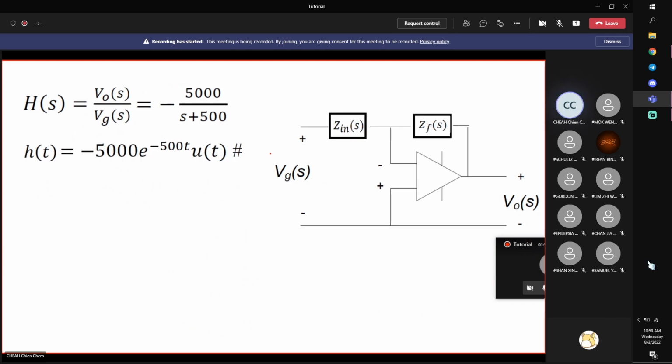First one is called unit pulse, which means that you pulse it. Imagine that you can do that, and then you want to check what your output is. In fact, this is relating to your transfer function only, right? Because the unit pulse in Laplace is equal to 1. So take the inverse Laplace transform of this, and you can see that this goes to 0, right? So it's finite.